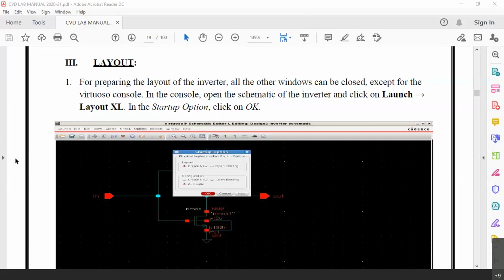That means when we simulate a circuit, we only have the SPICE model for the circuit. I hope you remember what is meant by SPICE. SPICE, simulation program with integrated circuit emphasis. So when you actually simulate the circuit diagram, it is basically the PMOS model, NMOS model, SPICE model. That is basically a mathematical model. And the model will have a symbol there, and the symbols are connected for a circuit diagram. Actually, when you perform simulation, it is the models only that are interconnected together.